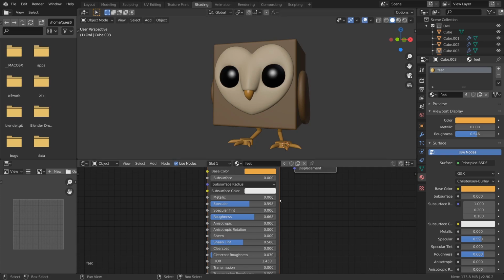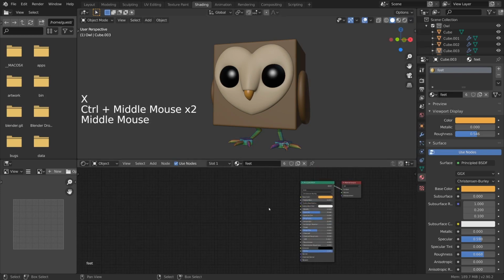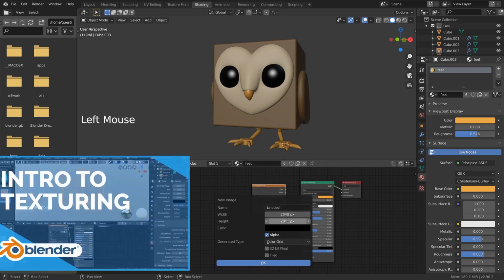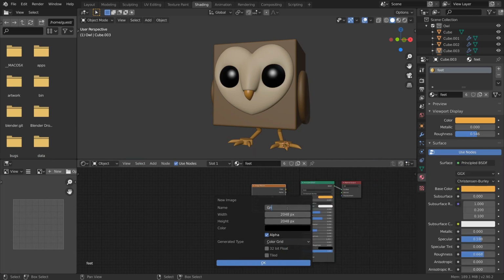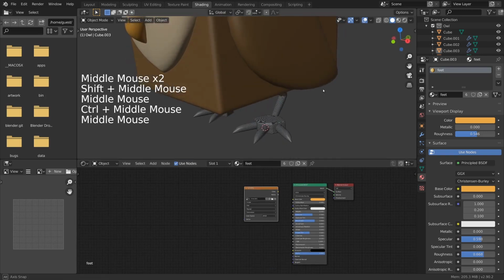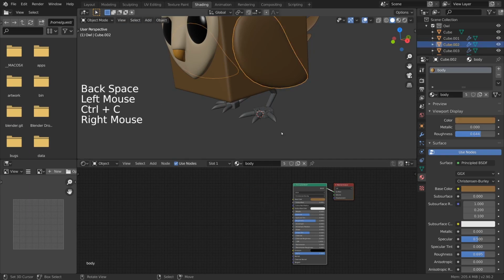preparing the UV maps. But first, switch the viewport color to texture, and it will use textures if there are any available in the material. Create a grid or color grid texture in the material to see stretching in the viewport of the UVs. As long as the texture node is highlighted as active and plugged in, it should work for both material preview and just textured workbench view. Copy the texture node to the other materials to see it on all of them.